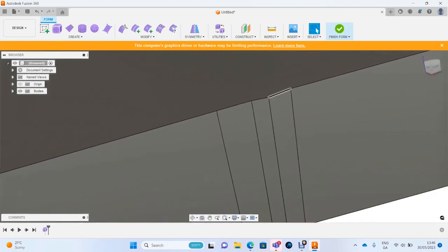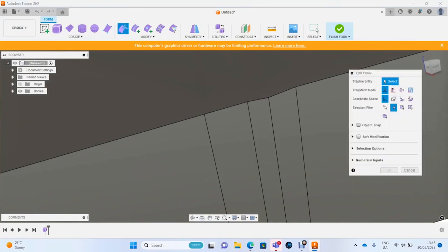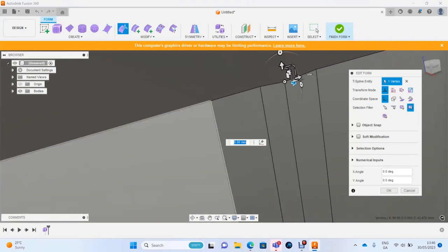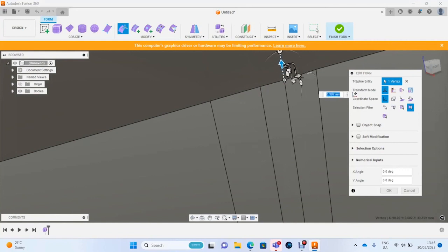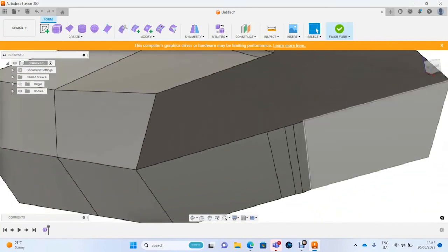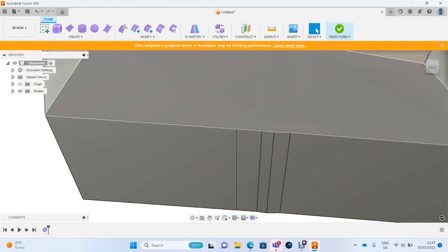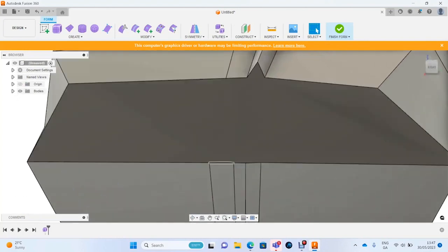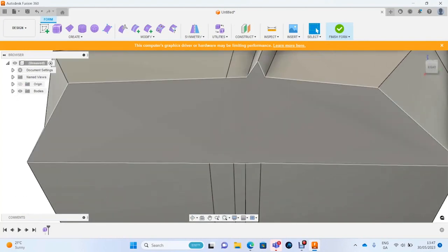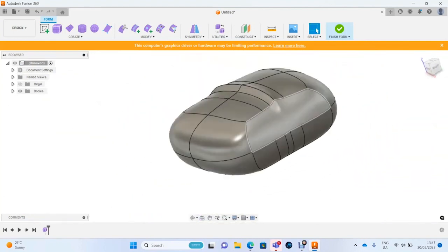And this is why Fusion's T-spline modeling is so powerful, because we have the ability here to have this T-junction, which actually isn't the standard. I don't know if it is anymore, but it definitely wasn't when this tool came out. You couldn't just have intersecting lines here, splitting a line in half. So you would have to continue this geometry the whole way around, and it would make the shape incredibly complex very early on in the design stages. Whereas Fusion allows us to avoid that issue.